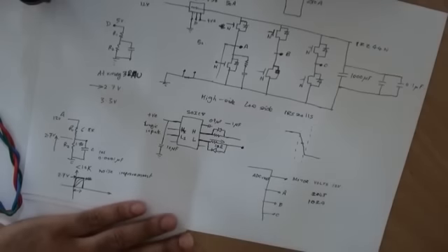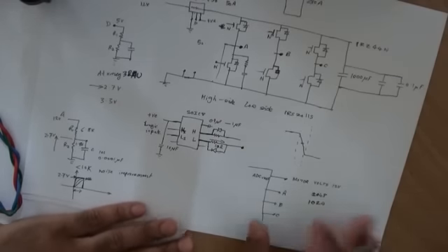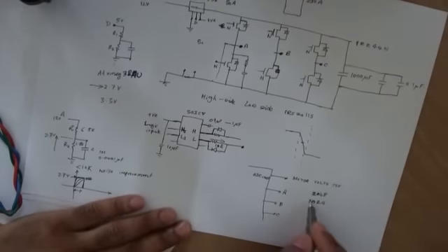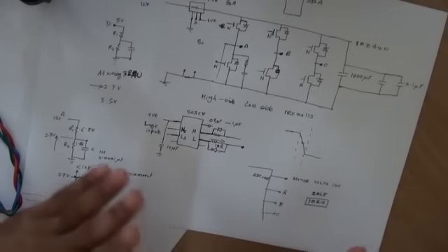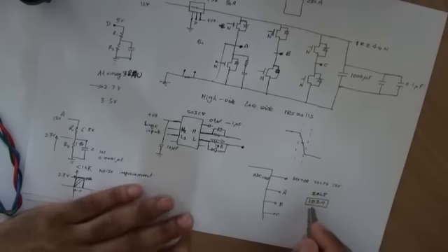So to detect a halfway, you need to look at 1024 nearabouts. You'll probably find after constructing that you will have to tweak this halfway value. Often it's more like 1020 or 1030. So to make the motor run smoother, you may need to adjust that value.